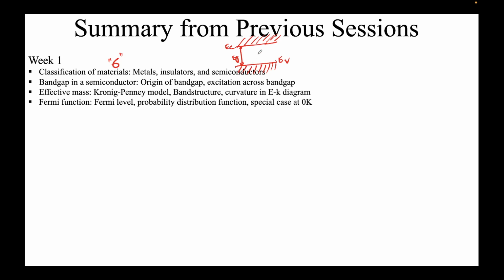And we can also excite the electron from the valence band to the conduction band, and the electrons can also recombine with a hole in the valence band and release a photon, which you saw is the basis for LED, right? But please note that the electrons in the conduction band are not free to move. Please remember they are in a lattice which may have some ions, and it will definitely face some kind of potential which we call the periodic potential, and we modeled it using the Kronig-Penney model over here.